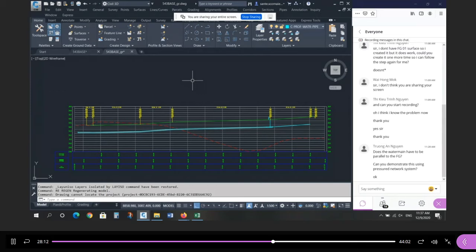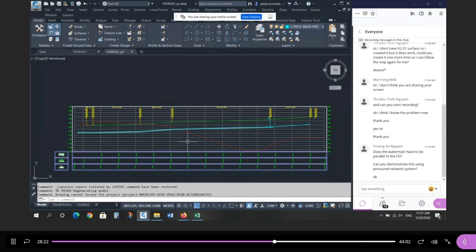So we're going to go from the hydraulic design using a spreadsheet, and then the geometry design using Civil 3D to draw the pipe. And then it'll be a little bit of back and forth. Like in the drawing, if you have to make a pipe steeper, then you have to go change the slope on the spreadsheet to match, and make sure that if you make it steeper, maybe you can make it smaller. If you make it smaller, then you can go and change the drawing and make the pipe smaller, and vice versa, right? Or if you flatten the pipe, it might have to get bigger.